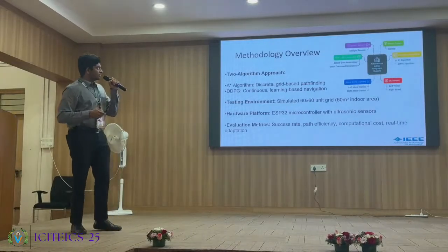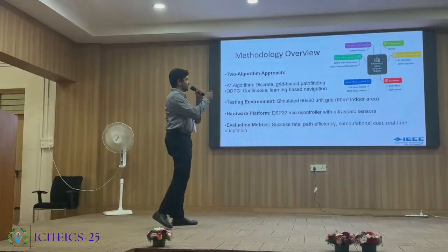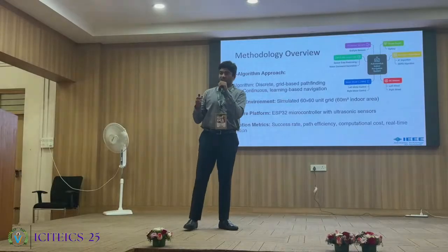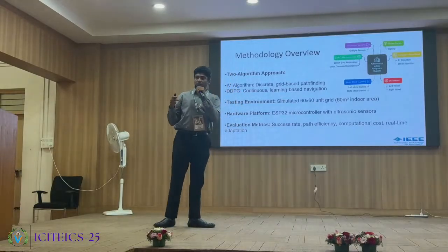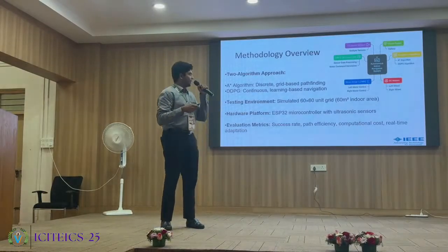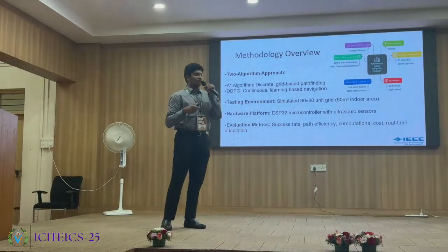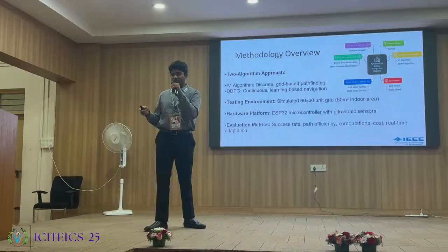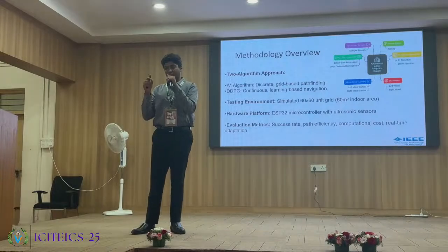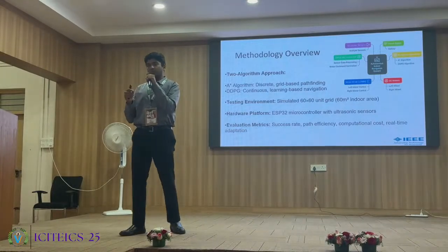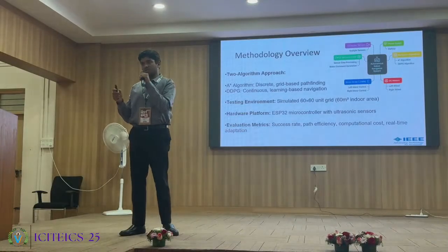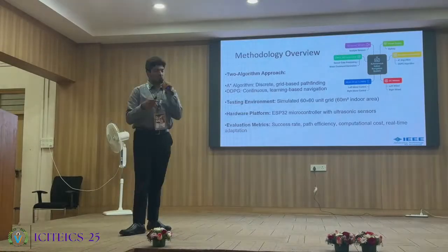This is our approach or methodology, in which we used various ultrasonic sensors for real-time obstacle detection, and ESP32 microcontrollers for wireless communication between our system and the prototype which we made. Along with that, both navigation algorithms have been implemented in our simulation platform. Through this ESP32 module, and using an L298N motor driver, a PWM pulse is sent from the ESP32 to the motor driver, and the battery-operated motors are used for moving the bot further.